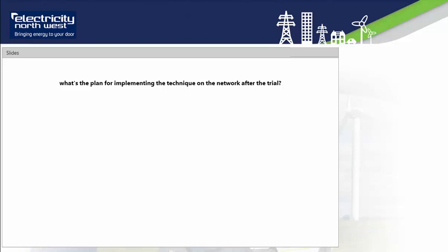Would this approach be viable for intermittent peaking generators? Okay, I'm not 100% sure, but I'll take the question, Paul. When it says intermittent, I presume this is implying generators coming on and off the network. Having a fault level assessment tool there, as these generators come on, assuming we have visibility of them via the SCADA system to show that they're connected, the fault level tool would carry out the assessment.